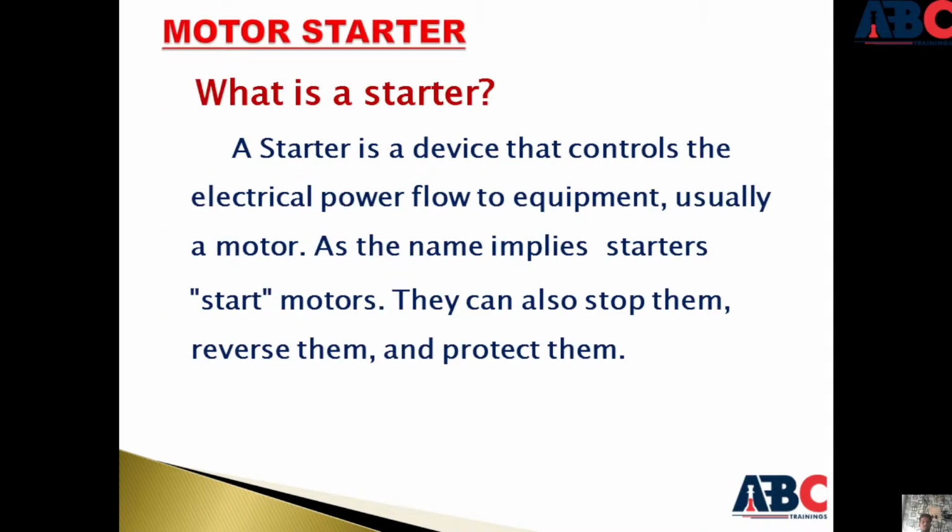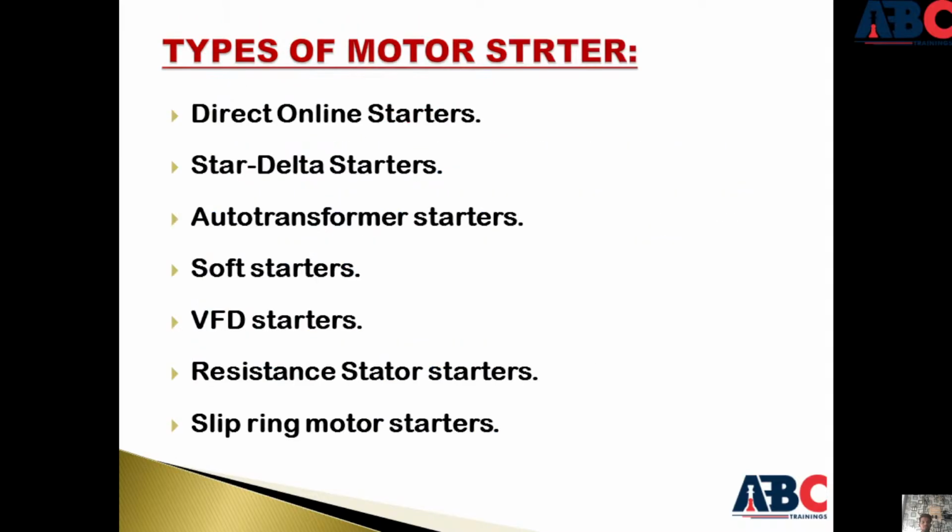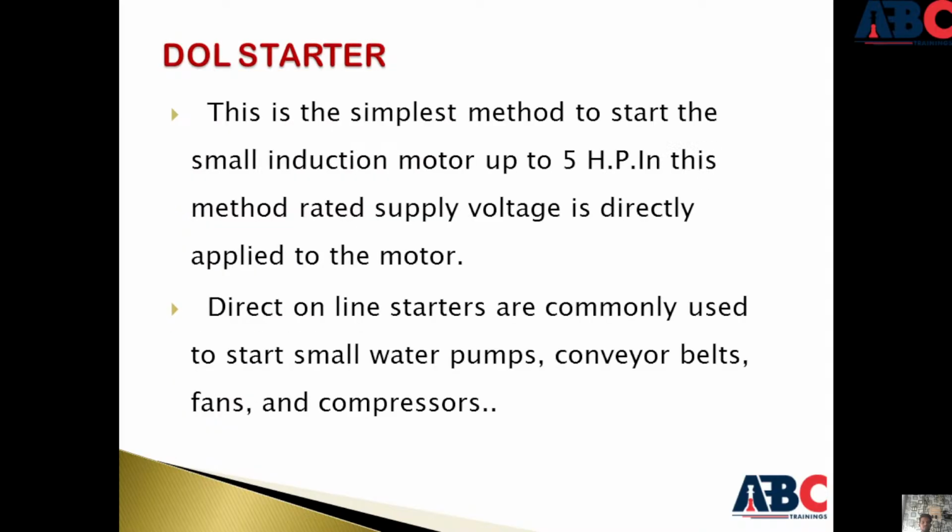What is a starter? Starters are devices that control the electrical power flow to equipment, usually a motor. As the name implies, starters start motors. They can also stop them, reverse them, and protect them. Types of motor starter: direct online starter, star delta starter, auto transformer starter, soft starter, VFD starter, resistance starter, slip ring motor starter.